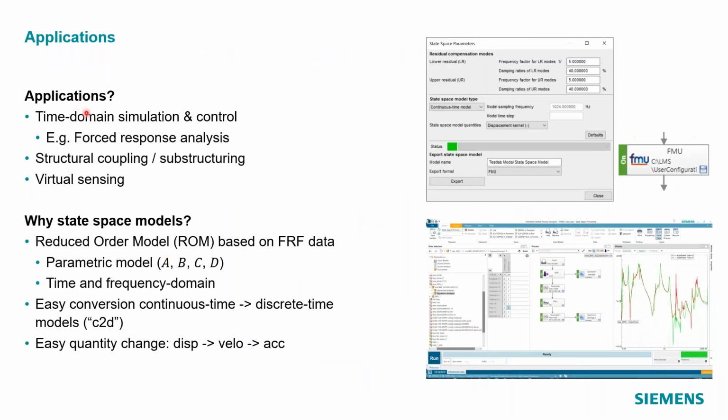What are the applications? So once you have a model, you can use it in time domain and frequency domain for simulations, for control studies. You can do forced response analysis, so you can apply an input to your state space model and calculate the output. It's used in structural coupling. That was a bit a damper case I showed before. Substructuring, virtual sensing is a potential use of the method.